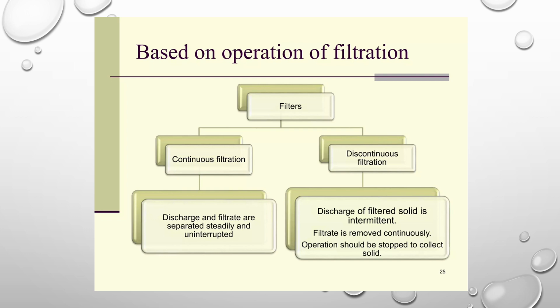Based on the operation of filtration, the filters are classified as continuous filtration and discontinuous filtration. In continuous filtration, discharge and filtrate are separated steadily and uninterrupted. In discontinuous filtration, the discharge of the filtered solid is intermittent, and the filtrate is removed continuously.